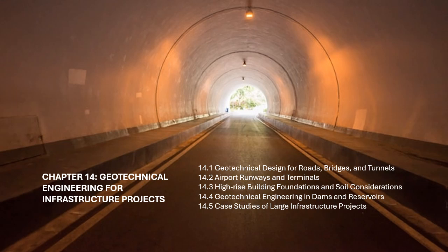Piles are designed to bear the loads of the building by reaching deep into stable strata that are capable of supporting the structure. The choice of pile type, e.g., end-bearing piles or friction piles, depends on soil conditions and load requirements. Caissons.